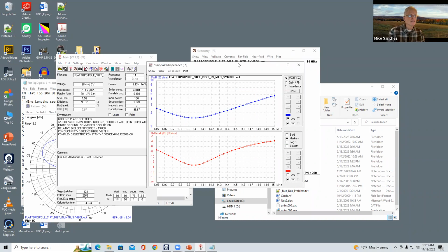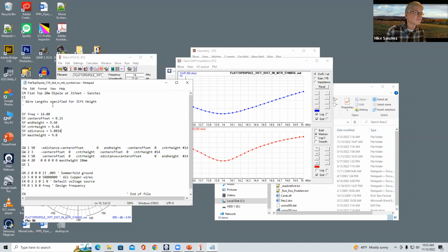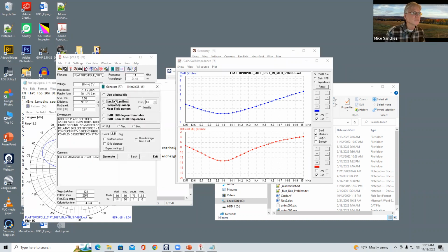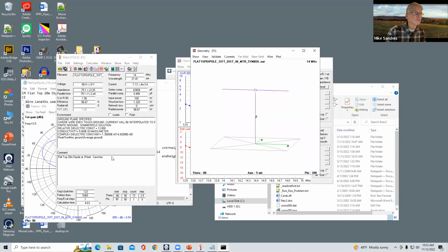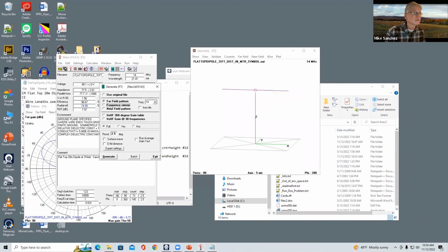I'm going to take just this, well, I'll do that in a second. So now let's take the other one, which was 5.0718, and recalculate the far field. That's always the first step. You'll get a confused result if you don't. And now let's do NEC output data, frequency sweep.